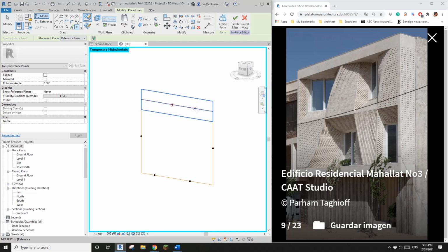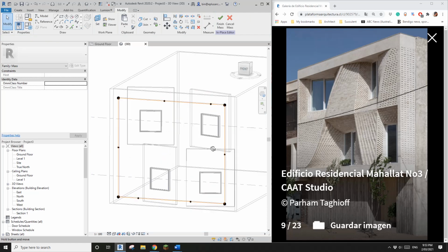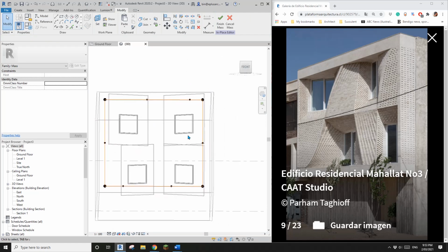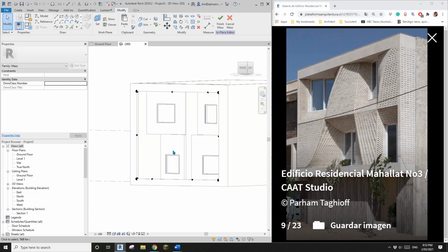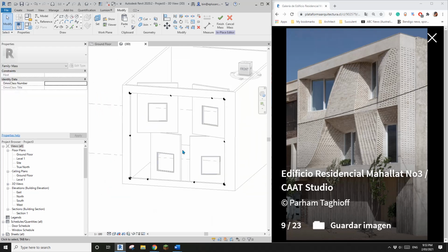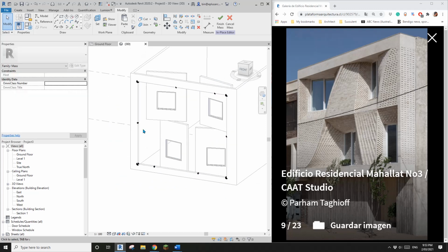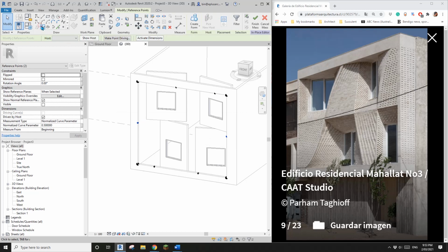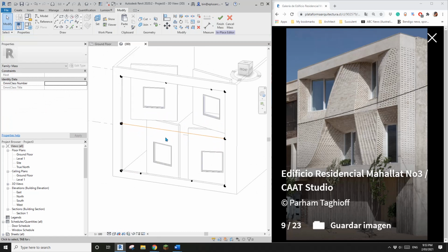Maybe here, maybe here. Okay, so now HR to turn everything back, and change it to SD shade or hidden line HL. So now we can continue work on this reference point and reference line. Let's create a reference line through these 2 points, make it a spline, and